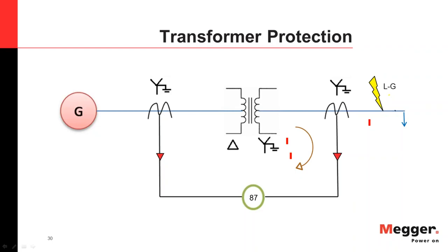We talked about the concept of zero sequence, negative sequence and positive sequence. And I told you multiple times that zero sequence is associated with line to ground faults because it's a neutral current flowing. Clearly you can see that this network has a delta winding, and a delta winding does not have a neutral here.